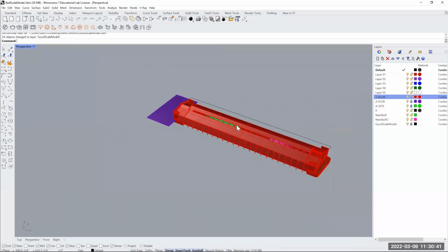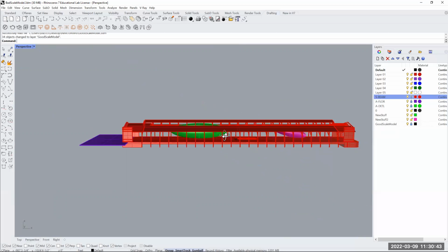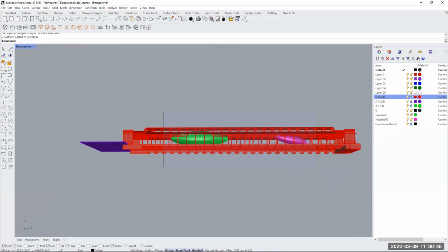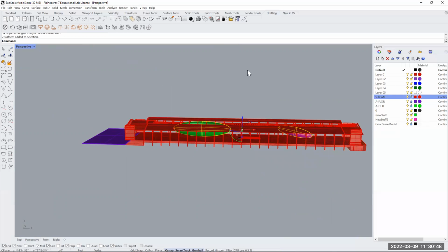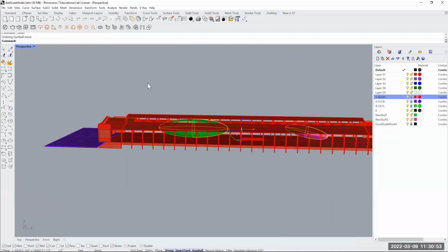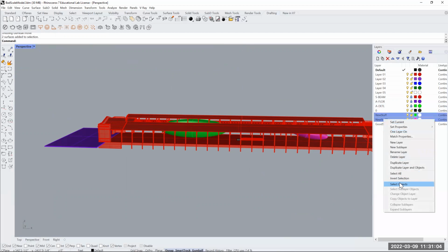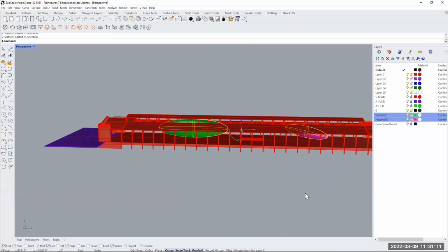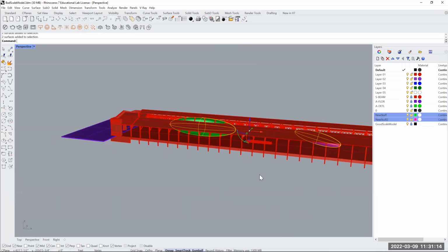So now, because everything is locked, you can select things in a couple of ways. One is selecting your project like this, making sure that you're selecting only your project, not anything else. You could do it manually like this, or you can also select two layers by pressing Control. So it's first layer, Control, second layer, right click, select objects. If you have more layers, you just Control another layer, and so on. You select objects and they're selected there. That's the way we're going to be selecting, but we also need a reference point.